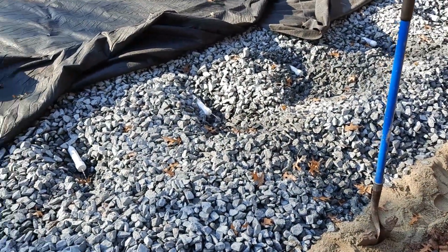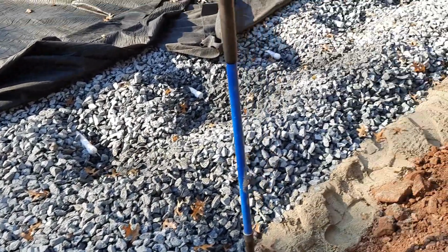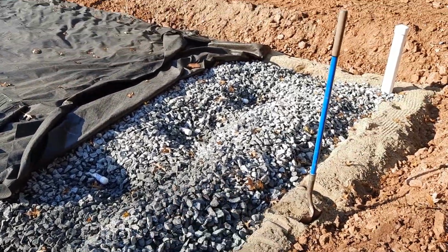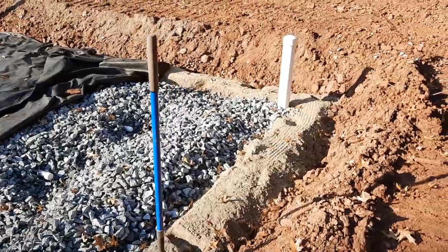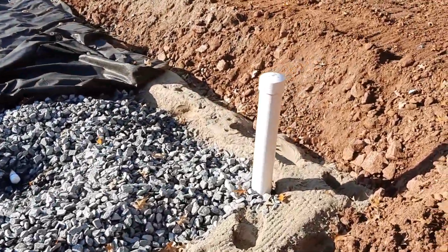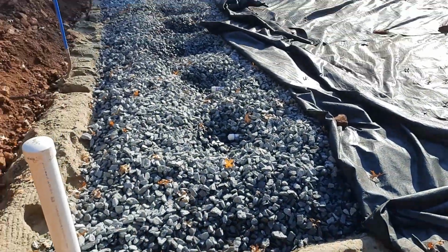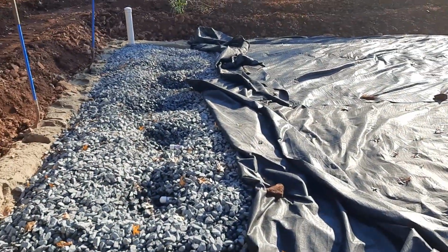So that's what you're looking for the pump run. You're making sure that the water exits at the very end over here. You also want to check the alarm. I heard it, but I'm not sure you could hear it in the video. But you want to check the alarm to make sure the high water alarm works. And that's the pump run.